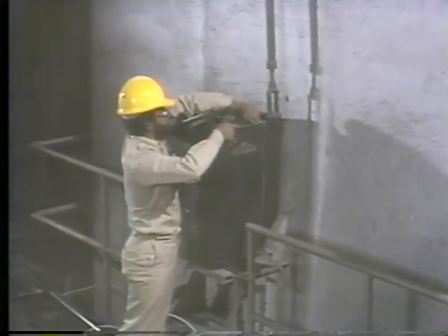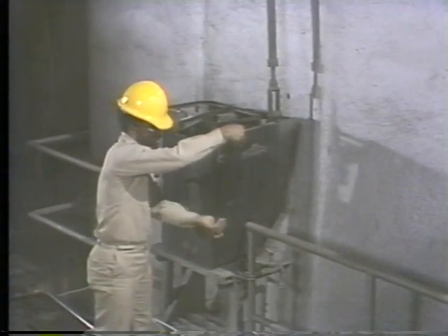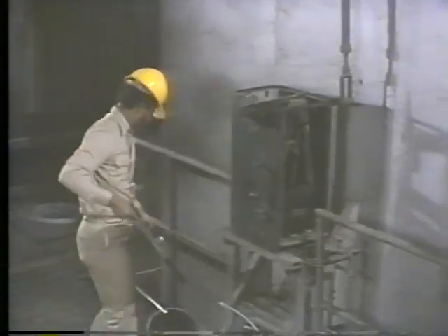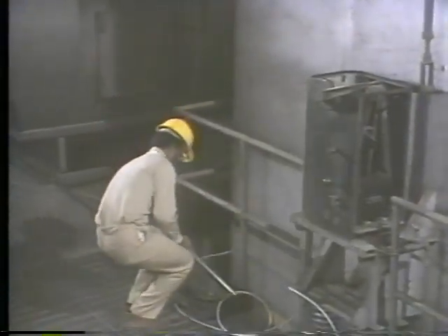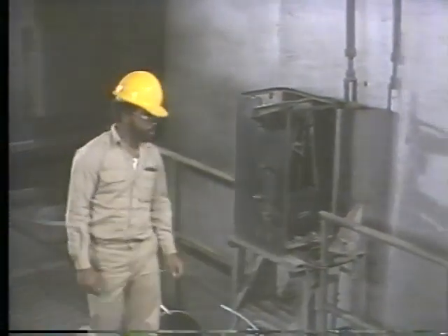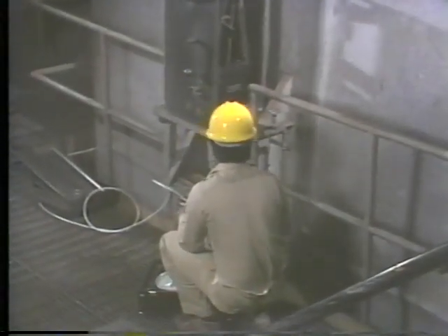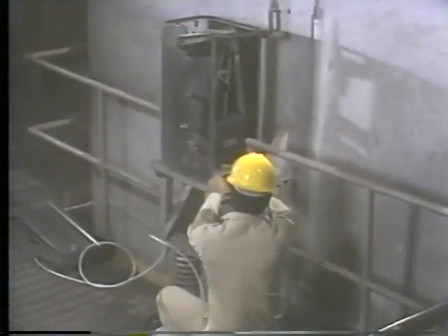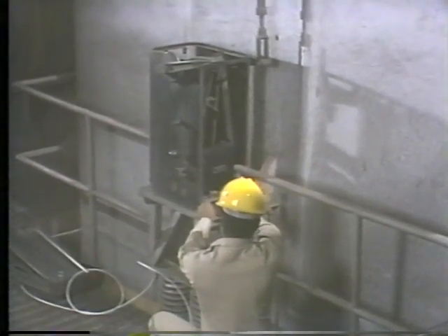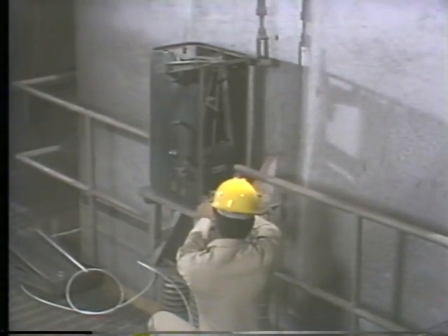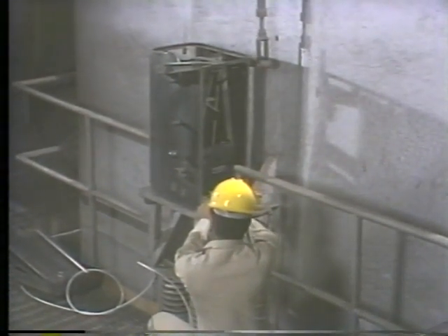Some mechanisms like this have mechanical locks that keep them from moving. The purpose of locking the instruments in place is to ensure the technician's safety until he's ready to make his adjustments. With this done, the technician can get to the actuator and positioner and be reasonably certain that the mechanisms won't move until he wants them to.